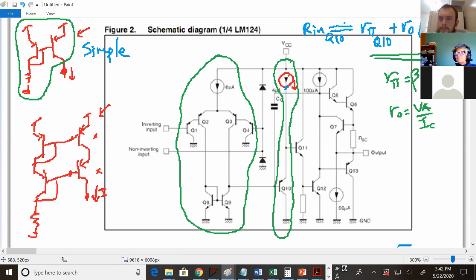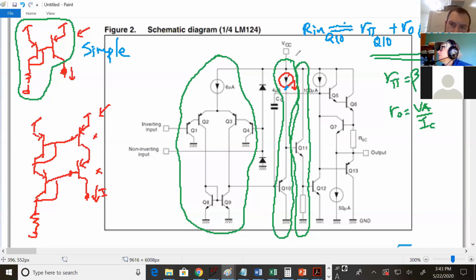Okay, so it probably included that because the diff pair was getting loaded. And then they said, oops, I just shifted my voltage up. And then, as you said here, this stage right here is, I'm still in green. I thought I was in blue. Oh, well. Another common collector. Then that one, yeah, probably just to shift it back down. No other function.